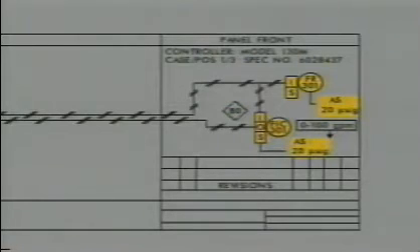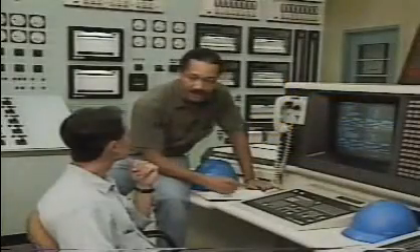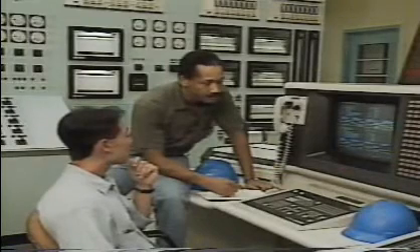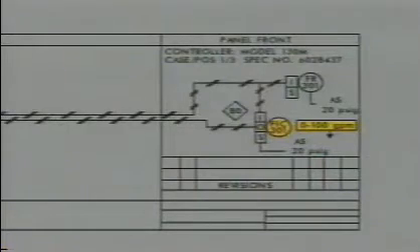Knowing the location and amount of supply air is important. You can tell which instruments have their own air supply source and use the information to isolate problems. The loop diagram also provides information about the operating range of the instruments in the loop. The information can be found inside a rectangle near the instrument to which it refers. In this instance, the range indicated at the controller is 0 to 100 GPM. That means the system is designed for a range of 0 to 100 gallons per minute.